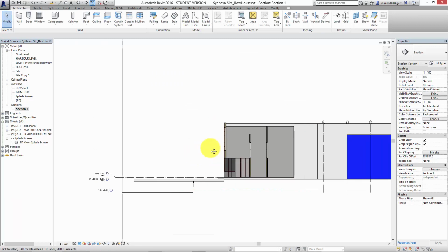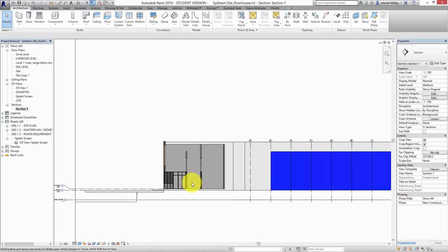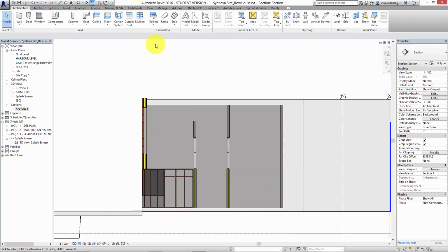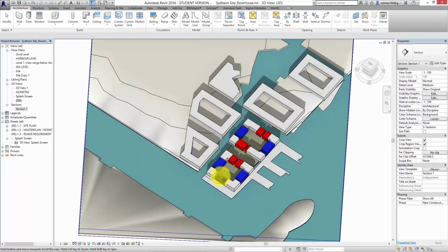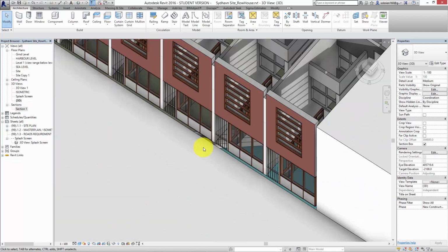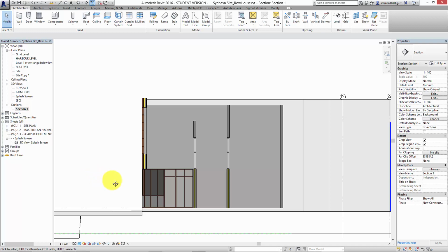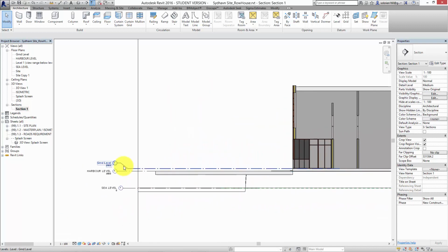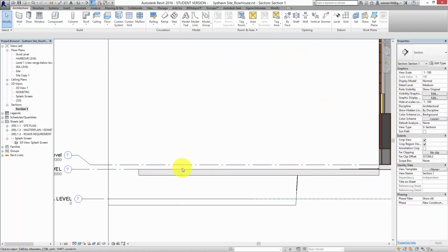And so now we've kind of cleaned up the drawing, and all we have in here is the site, annotations, and the individual linked models, okay, which are still there in the overall site, like that. Okay, so let's go back in here. So then we can see that the ground level we inserted is shown as level 2.3.